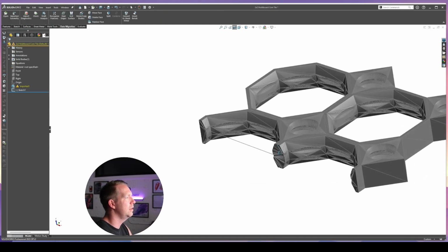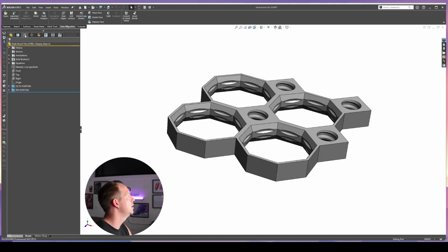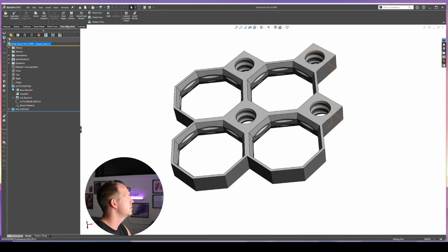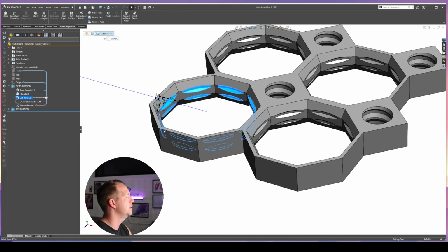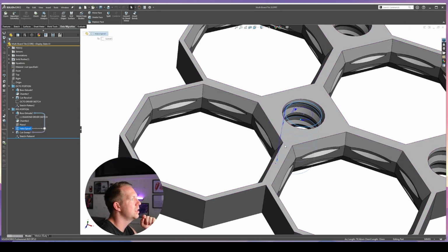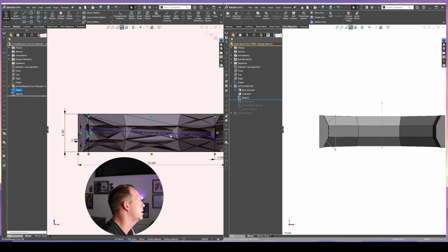This file that I've inserted here, this was an OBJ file. And if I go through to this one, this is my multiboard tile. Now what we have to do is change this cut revolve, because we now know it's not a cut revolve, it is a threaded cut. So we have to do a similar process to what we did with the threaded hole in this section and replace that element there.